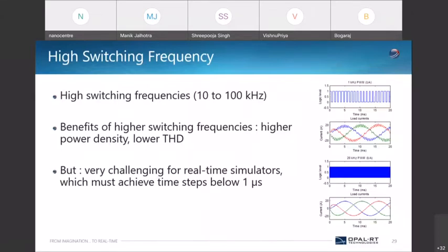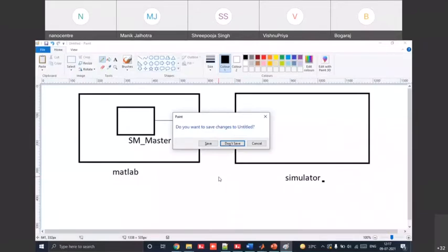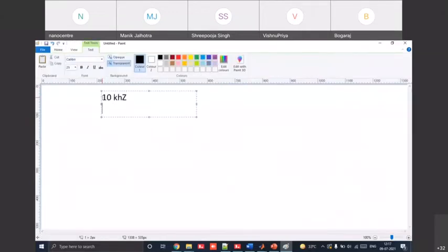So as a solution, I won't say a proper solution, but a test guide: let us say the maximum switching frequency of my model is 10 kilohertz, and we all know the Nyquist criterion says that the sampling frequency should be at minimum twice the highest frequency. So for our model running at 10 kilohertz, to satisfy the Nyquist theorem, we want the sampling frequency to be 20 kilohertz.